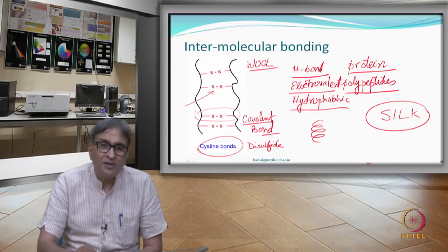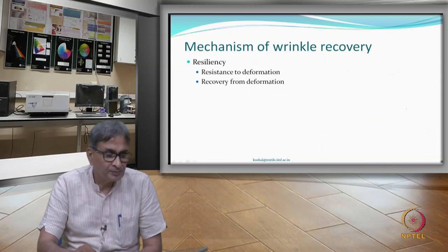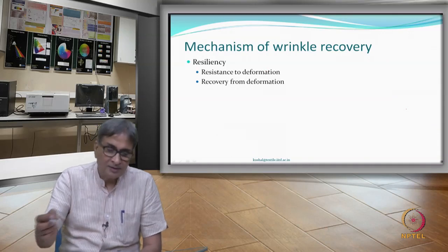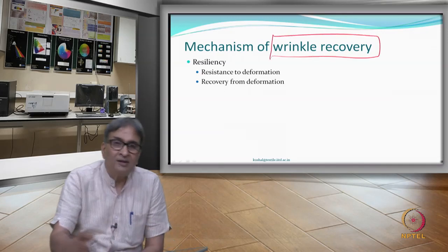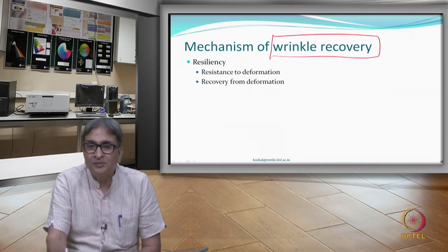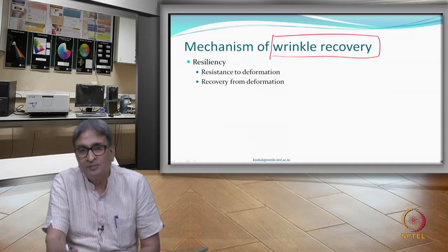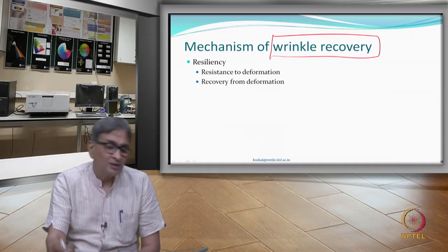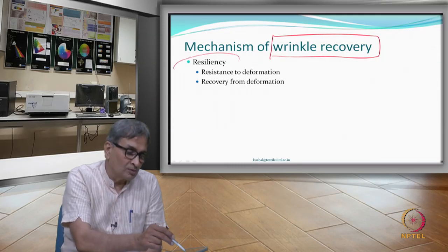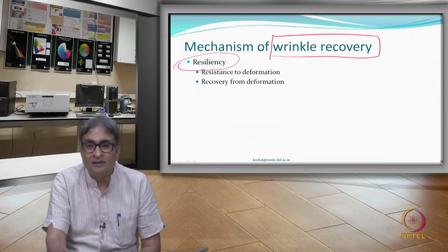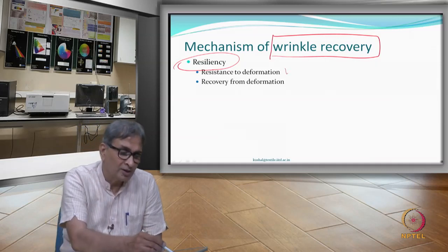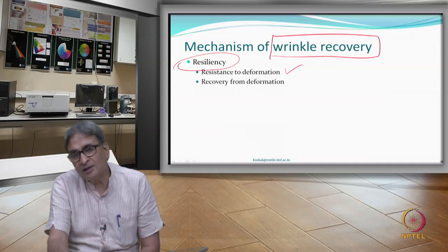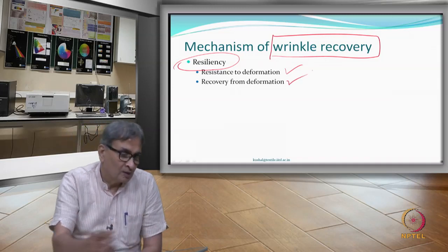So, what is the interesting thing which is coming out? One is we are more interested in recovery from any wrinkles that have been formed. There is a term which is used, called resiliency. Resiliency has two components: one is resistance to deformation, the other is recovery from the deformation.